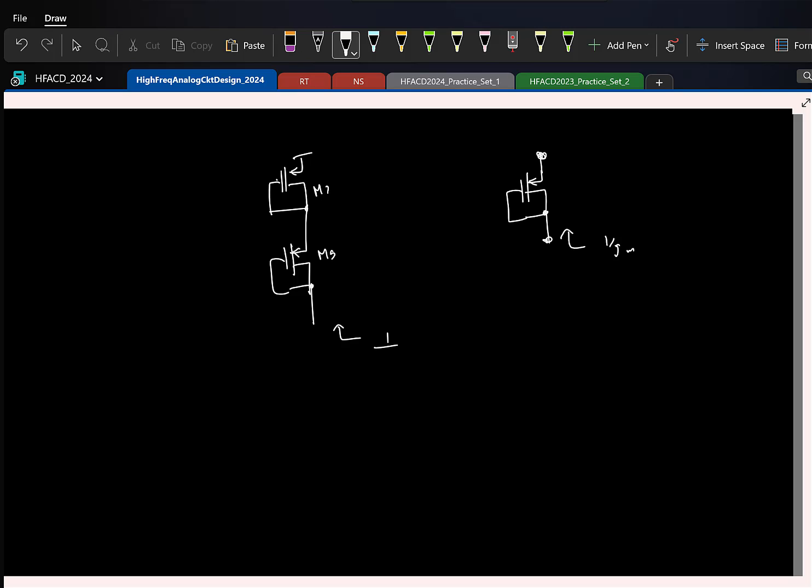For a linear one port network, how many parameters do you need for characterizing? Resistance. So anytime you see this guy, you know that this guy is disguised as a resistor. That's all, right? So I can replace it by a resistor. Similarly, this is a resistor. So this is basically a series combination of these two.